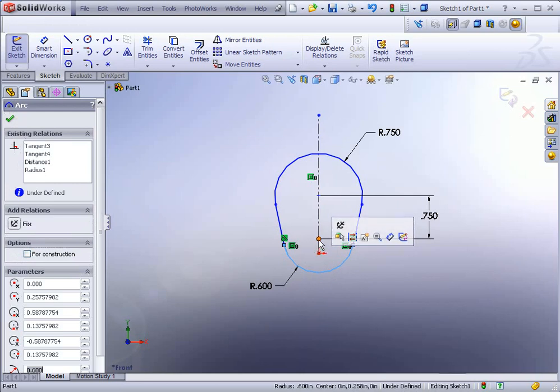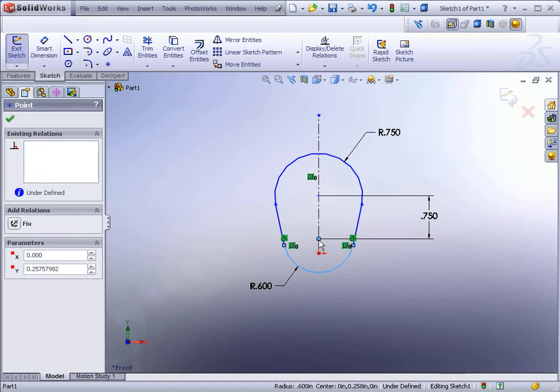Grab that center point. Now here's a little piece of advice. You're going to drag it with the left mouse button depressed over it. You have to be very accurate. The tip of your pointer has to be right on that dot. And you're going to drag it down. But, a little hint, SolidWorks doesn't like short distances to move or drag.